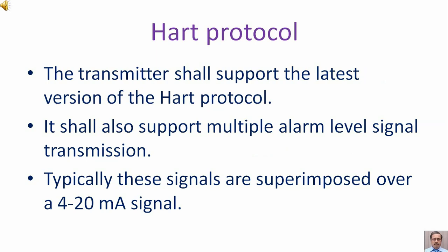HART protocol. The transmitter shall support the latest version of the HART protocol. It shall also support multiple alarm level signal transmission. Typically, these signals are superimposed over a 4 to 20 milliampere signal.